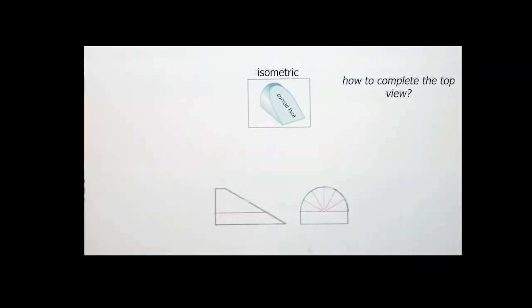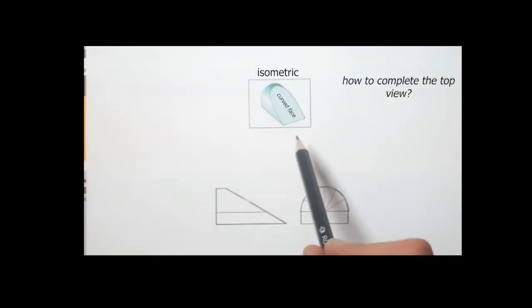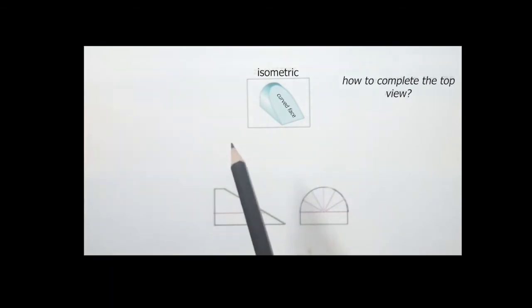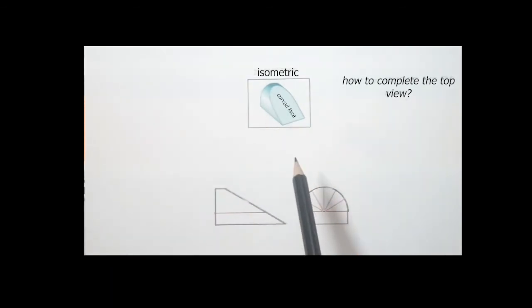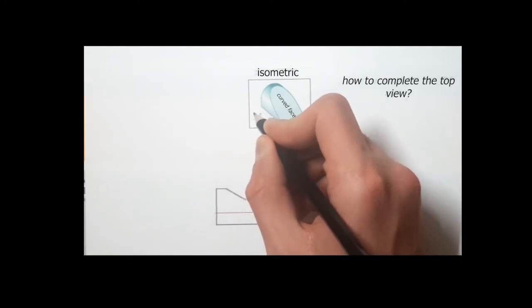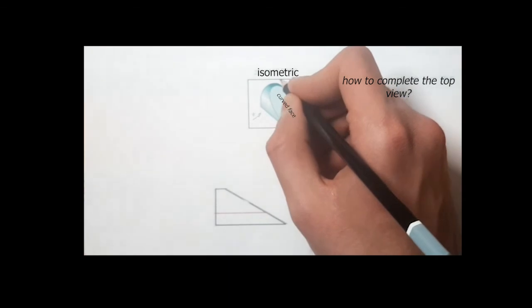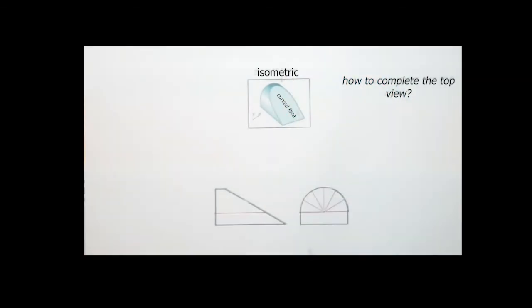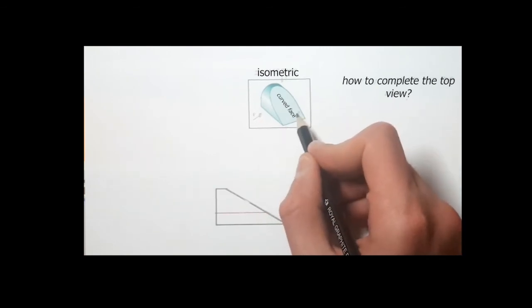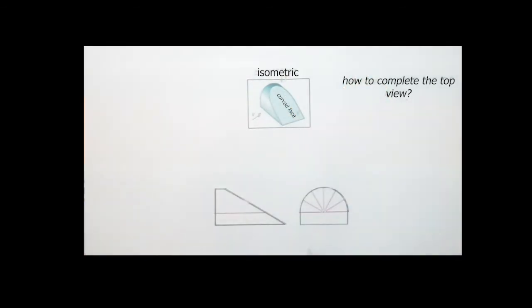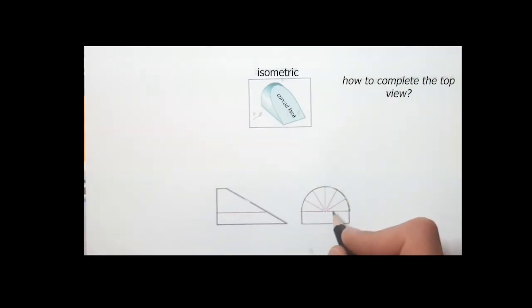We now have the isometric view, the front view and the right side view of an object. The curved face in the isometric view introduces a lot of confusion for students. We have the front view viewed from that angle, the right side view viewed from that angle, and the top view that we are supposed to get viewed from that angle. Front, right, top. I see that in the right view given to me, the circle, the feature, is seen as a semicircle.